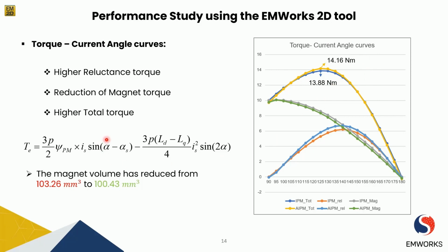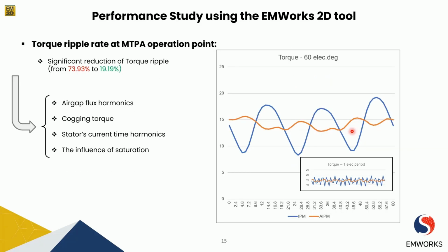And from the perspective of the shifting phase, the shifting angle, as you can see here, has been a little changed. In the literature it has also been shown that the focus was on torque improvement instead of only torque production, which we have shown and analyzed in the next step, where we achieve a significant improvement in the torque ripple rate.